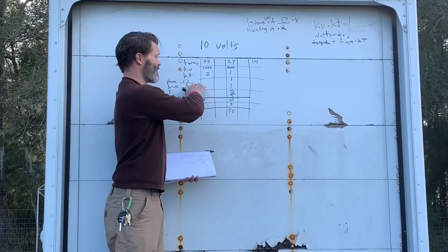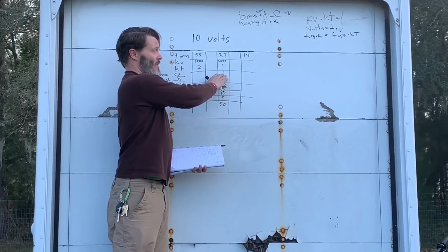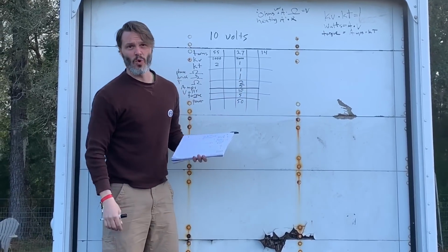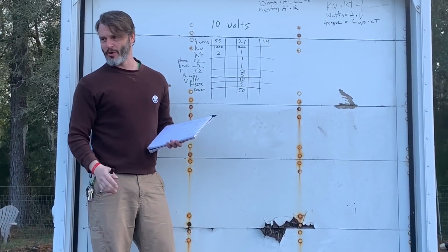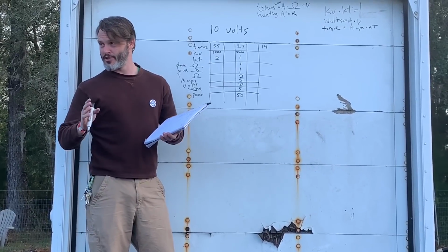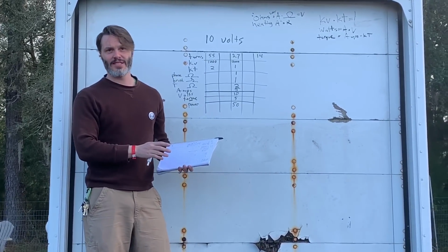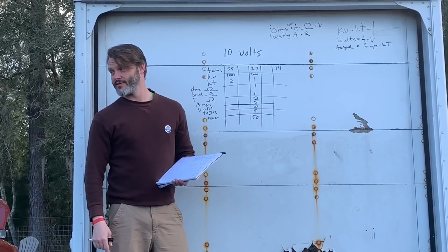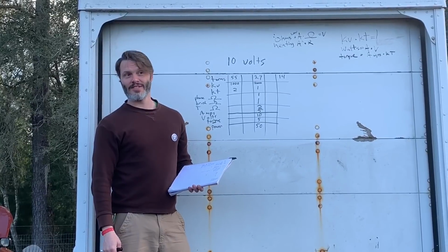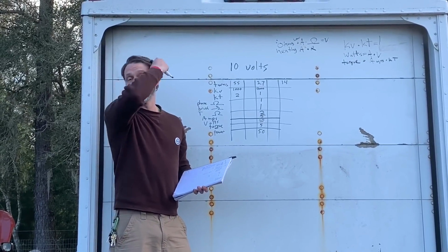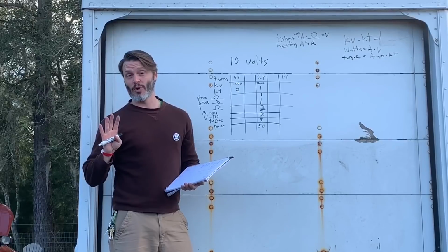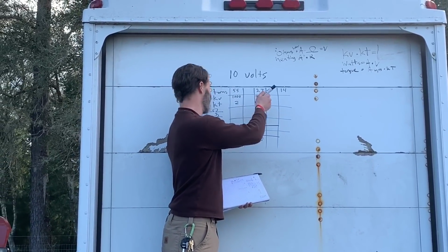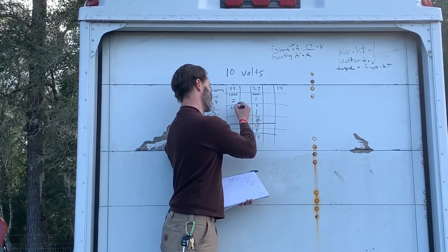Now, the next one, our phase resistance. If you halve your motor speed, and we start with, of course, the phase ohms of 1, what would y'all guess that the new motor resistance in the phase would be? So we're starting at 2,000 KV, we're going to half speed to 1,000 KV. What is our resistance going to do? Double? Good guess. Half? Good guess. Anybody else? I mean, that sounds reasonable. So what's going to happen is it actually goes up by 4 times. It's a little weird that it does that, but when we look at some of the other formulas, it actually works out. So 4 ohms.